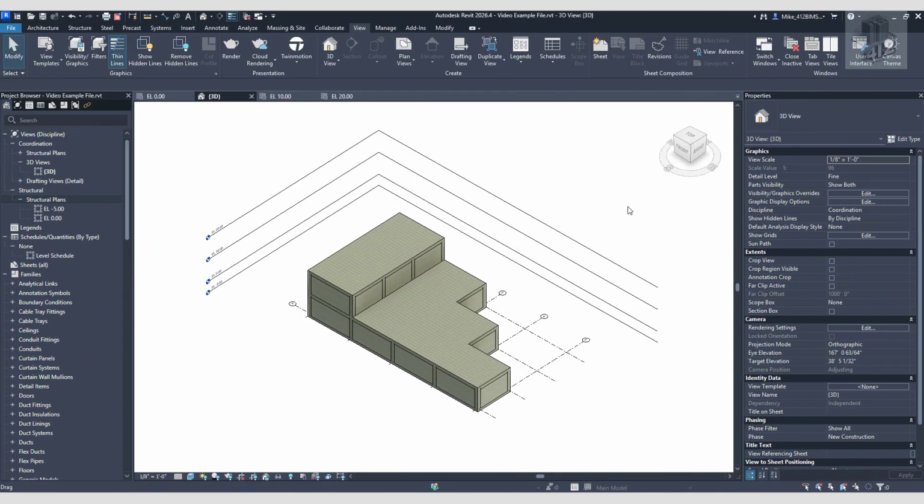In this video, I want to talk about the 3D and 2D extents of levels and grids. When working with Revit Levels and Grids, it's important to understand the difference between their 3D and their 2D graphics. The 3D extents are visible in 3D and 2D views. And while you can adjust them in the 3D views, the controls aren't precise and you can't edit them together like you can in a section or an elevation view.